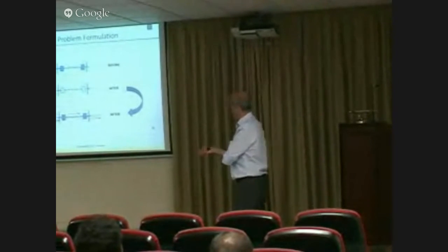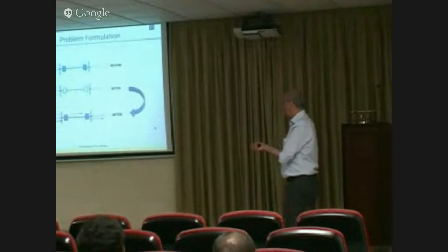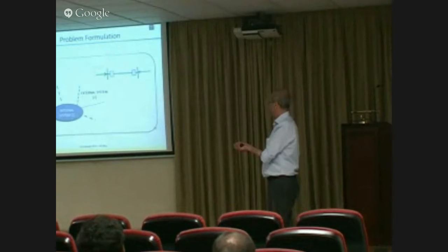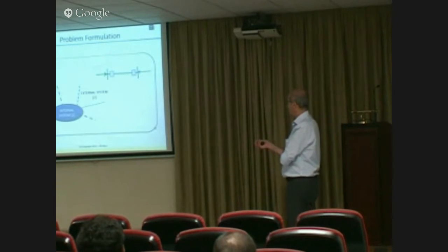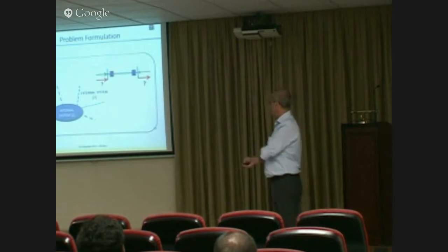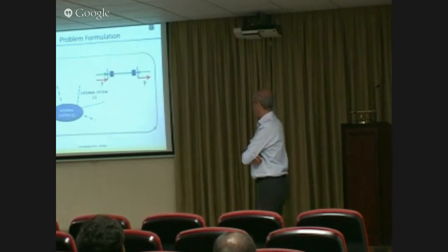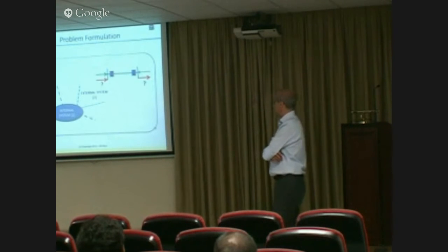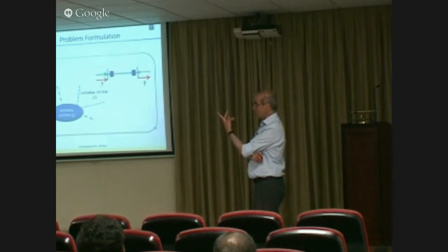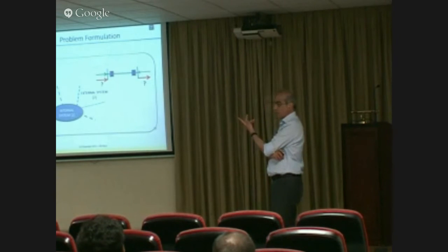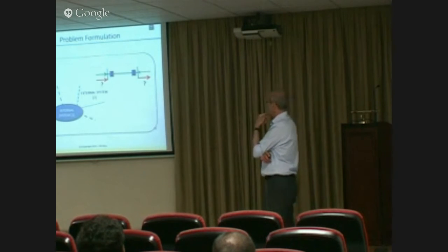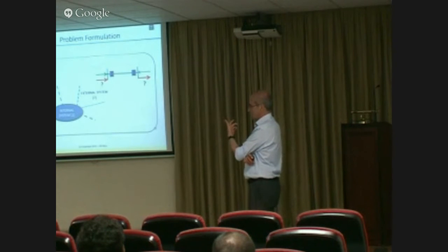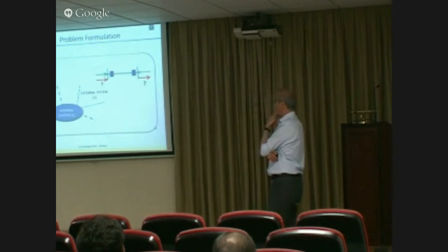So this equivalence can help us in identifying an external line branch outage, because if you think about it, essentially a line outage will be equivalent to a change of a pair of injections at the terminals of this outaged branch. So the branch remains closed, but you notice this jump in the injections at the terminals.